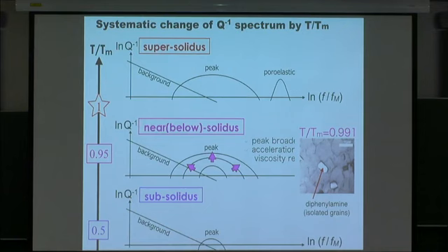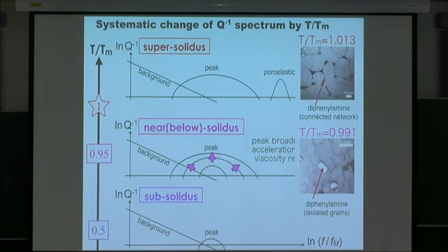In contrast, in the microstructure annealed at 1.01 homologous temperature, a connected network of melt exists at triple junctions. So these changes at 0.95 are caused by a solid state mechanism.